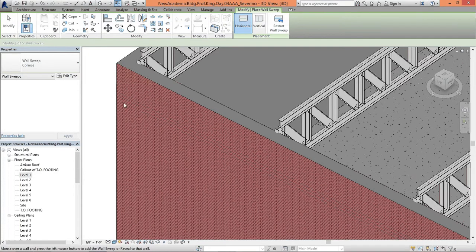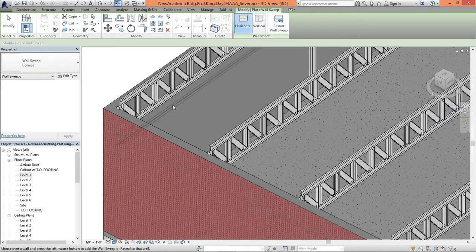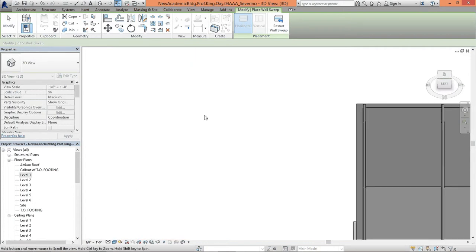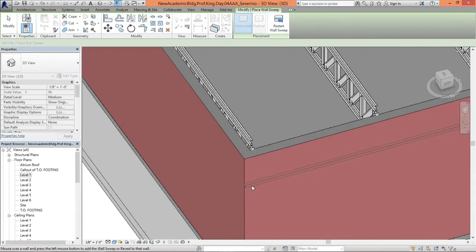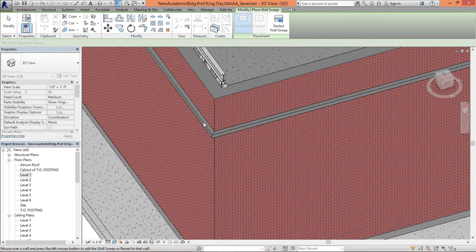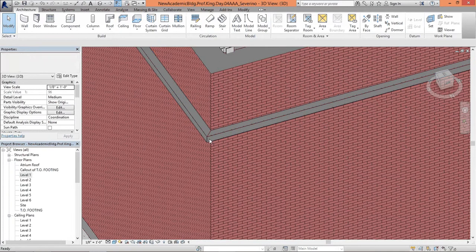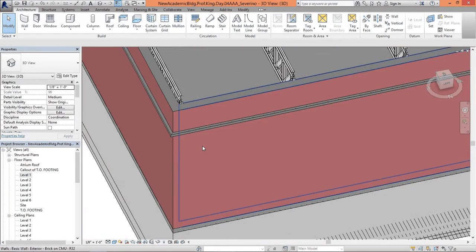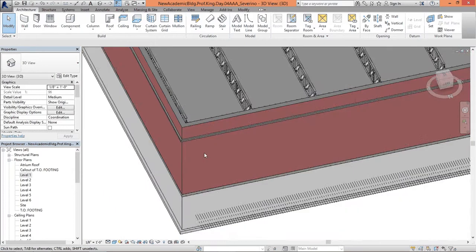You can already see before pressing that it turns gray, so it's going to be more of a rectangular, if not square, profile. So that allows you to place it more freely throughout the wall, and you can even place it in the other walls. A good thing is you can place it here, navigate yourself to the other side and make it also in the other wall, and in their meeting point this will be a fillet, with a little angle detail.